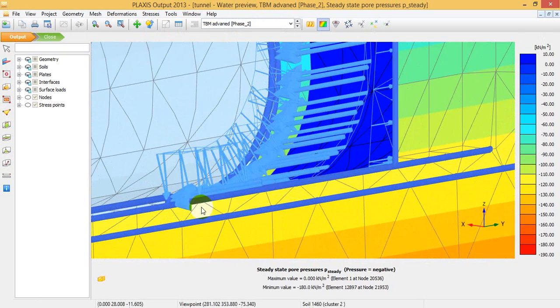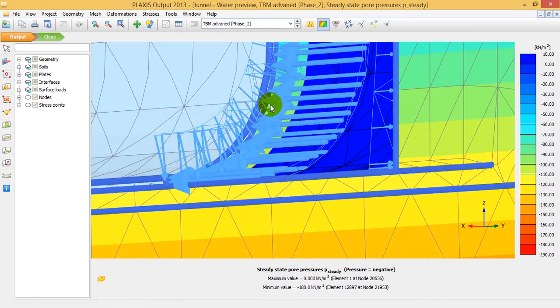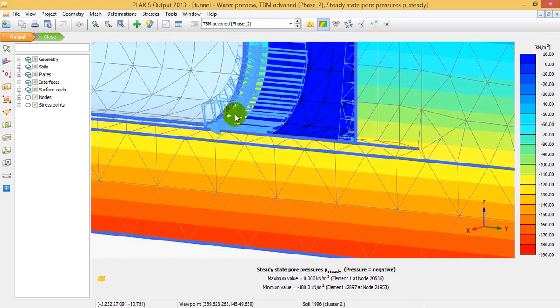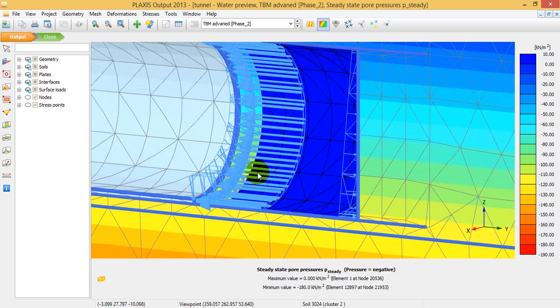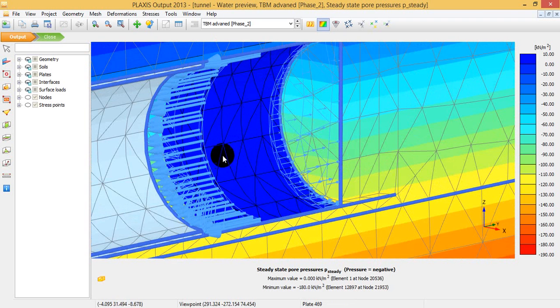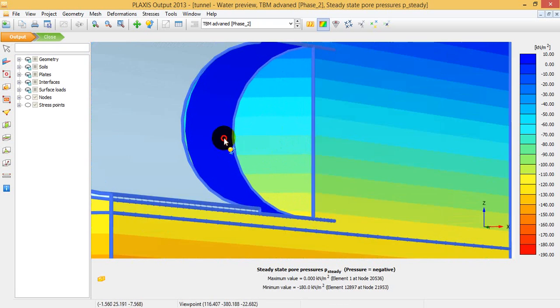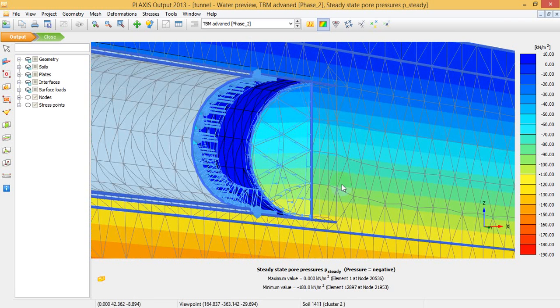segment which has jacking force along it, and also has a grouting pressure here, which is illustrated here, which increases versus depth. This is the segment, which I define with a plate. This is the body of the tunnel, and it has a contraction which decreases versus the length of this part of the machine. And finally, this is the face of the tunnel, which I define using perpendicular pressure. Okay.